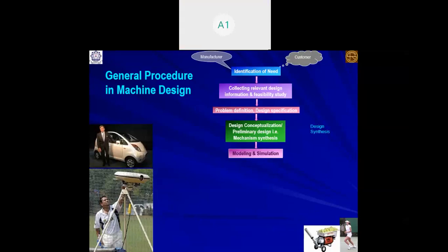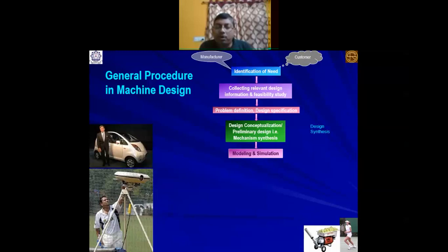Torque may also be considered, sir, how much torque is required. Along with RPM, torque is required, and power is a function of the torque and the RPM. Clear? Yes. Power, as you mentioned, is the derived quantity and it is a function of the torque and RPM. That means RPM is required along with the torque. How much torque is required at the crank end.